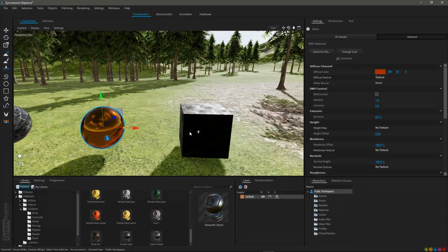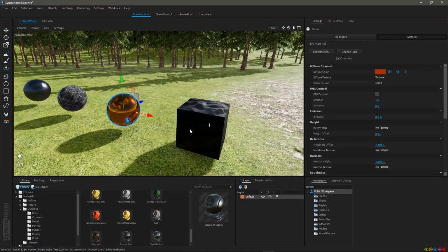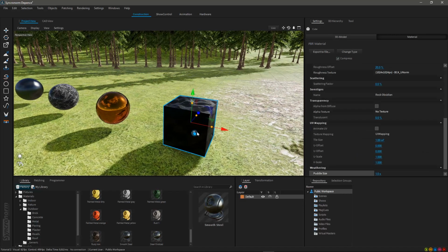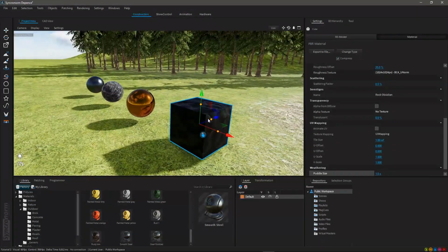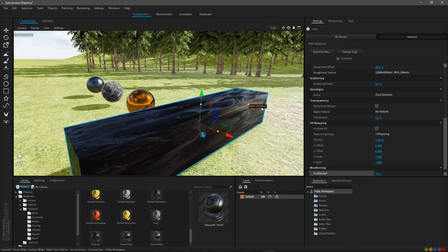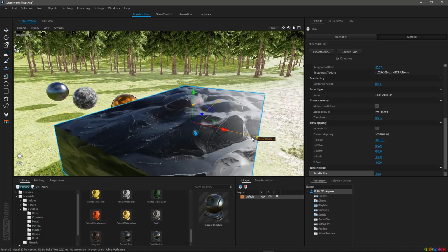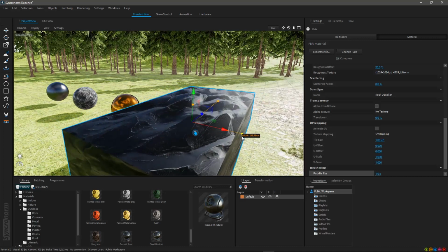Some materials already come with the information whether to use box or UV mapping. This mostly is true for materials which are dedicated to being placed on floors. For example, you can scale those materials and transform them as you like, while the textures will be deformed using UV maps. Using box mapping, you can avoid this.